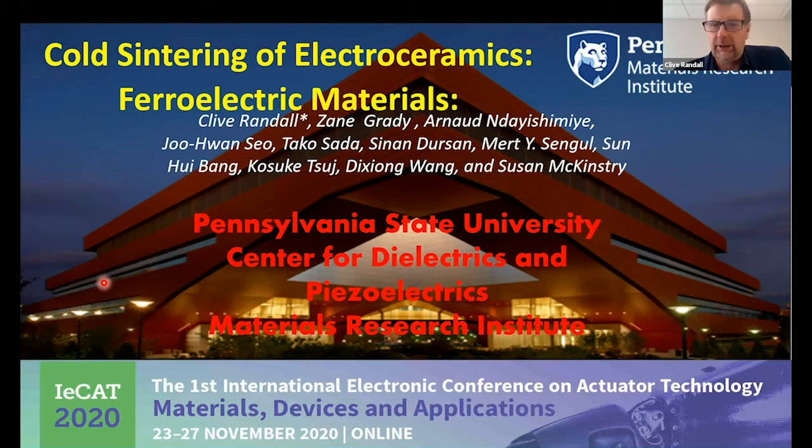As Kenji already implied, the actuator business has been around for a long time, particularly driven by the piezoelectric effect. And what I think you see today is that there's a lot of new things happening in terms of particularly the materials processing. And that's where I'm going to start, to discuss a technique which we started to develop about 5 years ago called cold sintering. And as of probably the last year and a half, we have really started to do very low temperature synthesis of ferroelectric materials. And that's what I would give a briefing on.